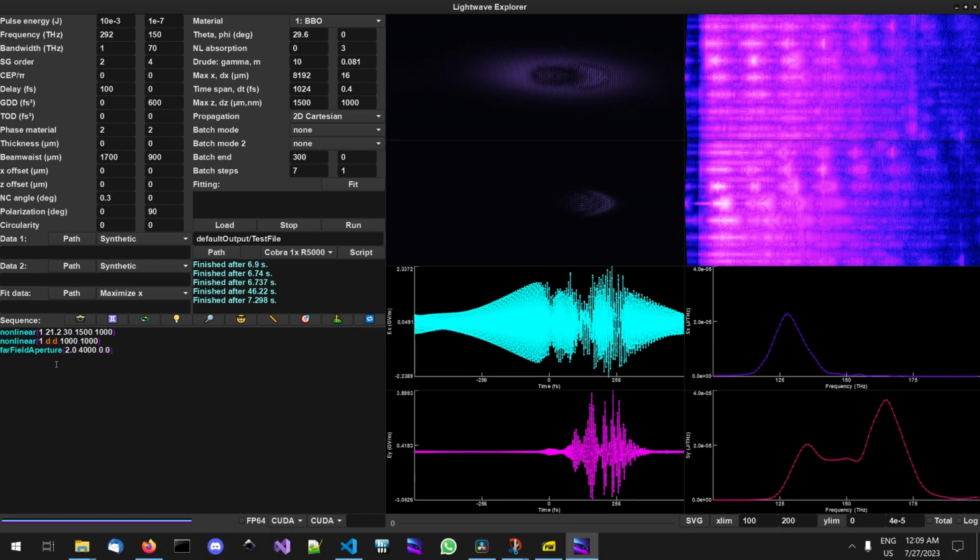To know what all of the inputs of these functions are, you have to look in the documentation. But in this case, we're only interested in the first one, which is the opening angle of this aperture. What we want to do is make this opening angle small enough that it's going to filter out our pump light. So we're just going to have an aperture in our beam which will only let the signal through and block everything else. And that's going to be the last step of our little sequence here.